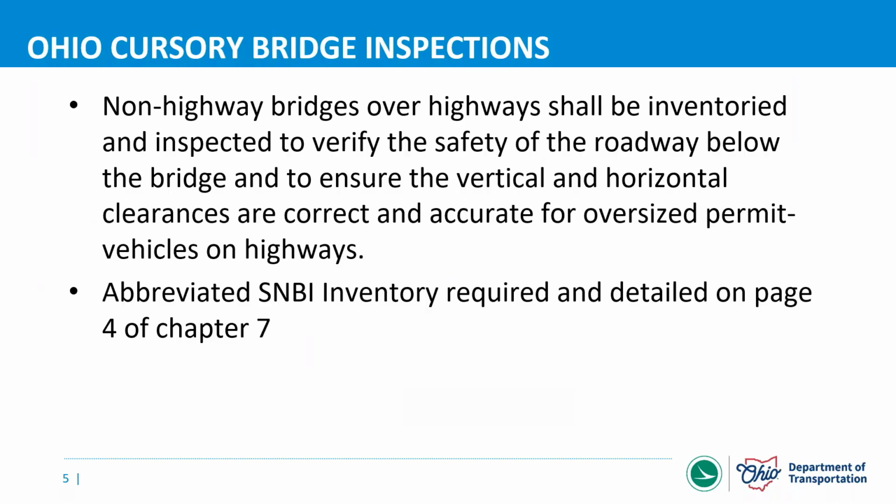So again, we want to inventory and inspect these for safety and to make sure that vehicles beneath are not subject to danger, but also can fit through the opening of the structure, right, for permitting or oversized vehicles, et cetera. Since these are not national bridges, they're not NBIS bridges, we're not required to do SNBI inventory. We're not required to inventory these at all per federal law, but for Ohio law, we are.